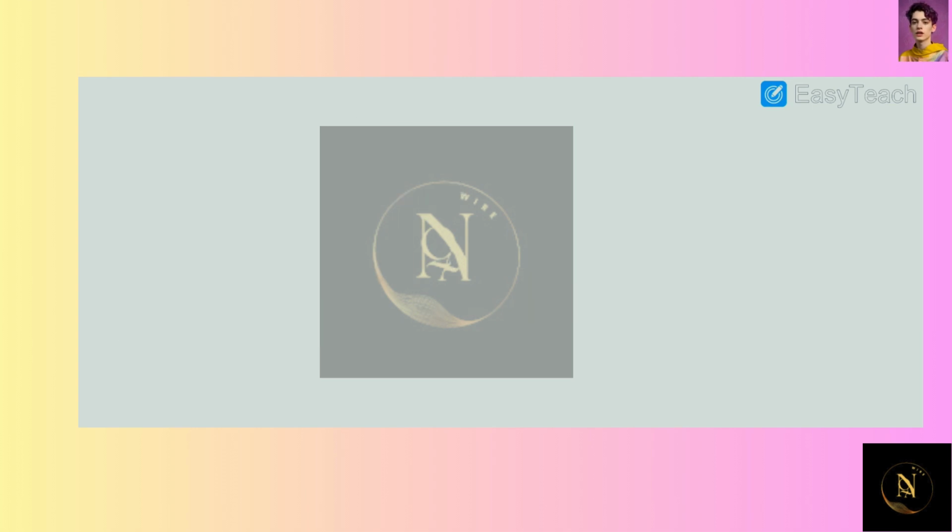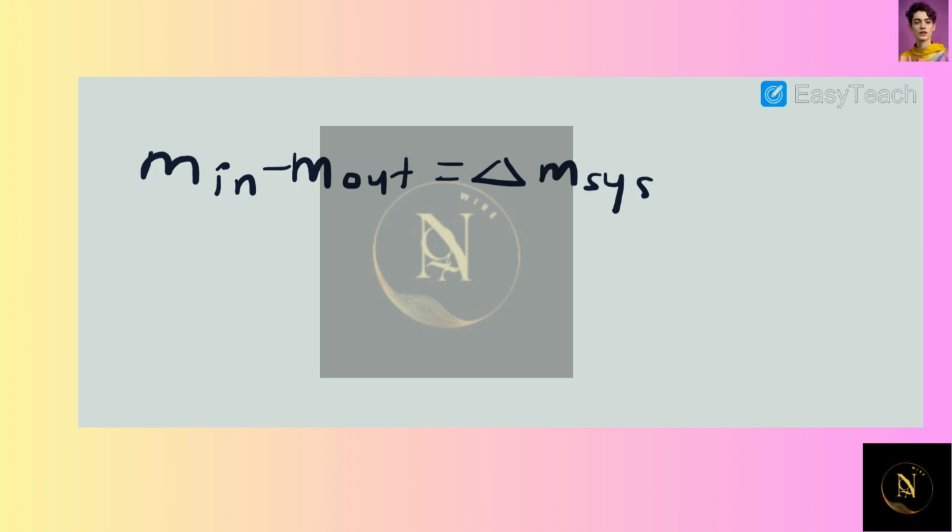So next, what we're going to do is take the cylinder as our system, and we're going to do a mass balance. So we can say that the mass coming in minus the mass leaving is equal to the total change in mass of the system. Now, we don't have any mass that's leaving, all we have is mass that's entering. So that's going to be simplified down into Mi is equal to M2 minus M1.